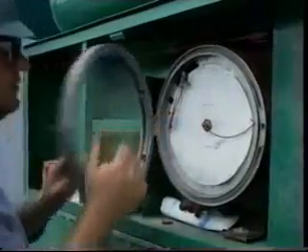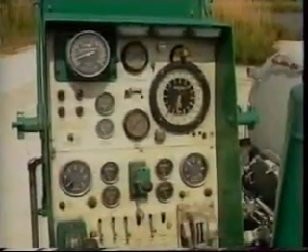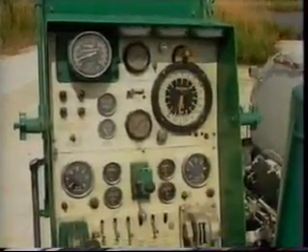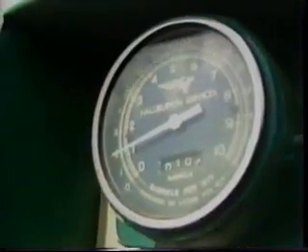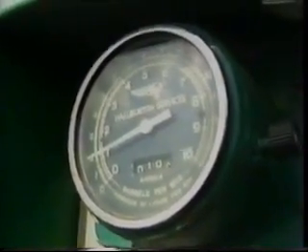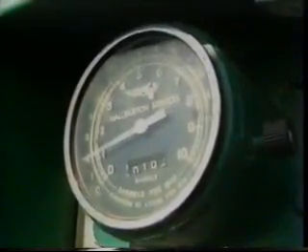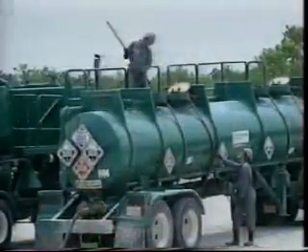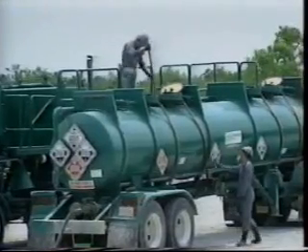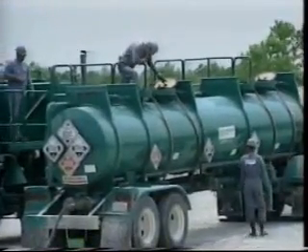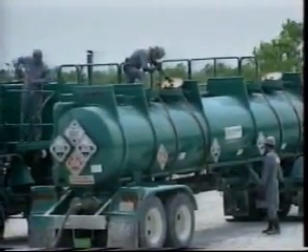Once the job has begun, injection rate and pump pressure are displayed at the operator's control station on the pump truck. Injection rate can be read directly off the gauge or calculated from pump plunger size and strokes per minute. The acid tanks are gauged throughout the job as a safety precaution to confirm the accuracy of the pump rate. All treatments should be closely monitored throughout the job. Let's look at some considerations.